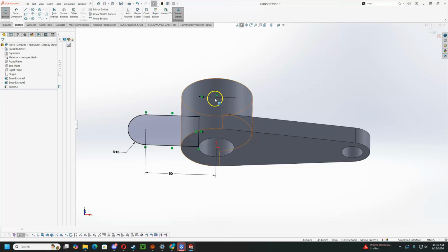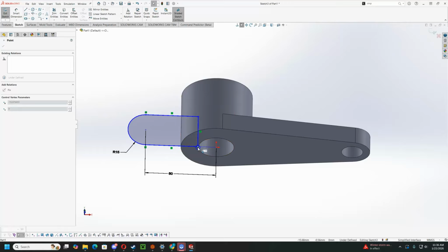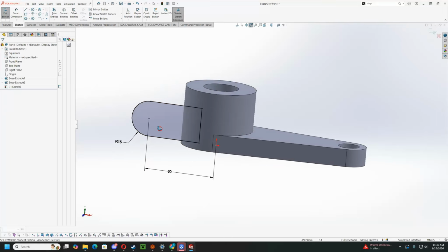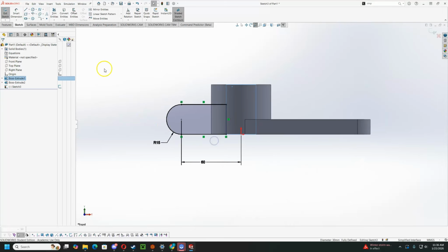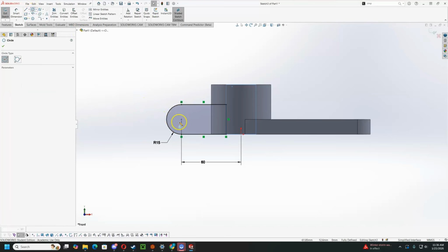And if it's not the case, you can convert that circle to a line. But in this case, I could just take this point and pin it to that edge. So if I were to delete this and let that float again, you can see it's actually still defined because it is coincident to that vertex. If I drag it free, it won't let me, oh no, it did let me drag it. So there, same result. The point is this line is connected to this circle, so it will always fill in the gap. Okay, we'll leave a small circle in the middle here.